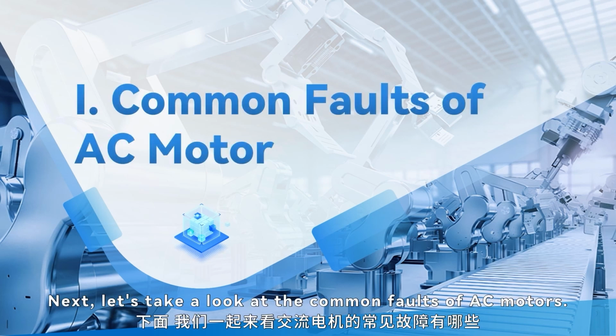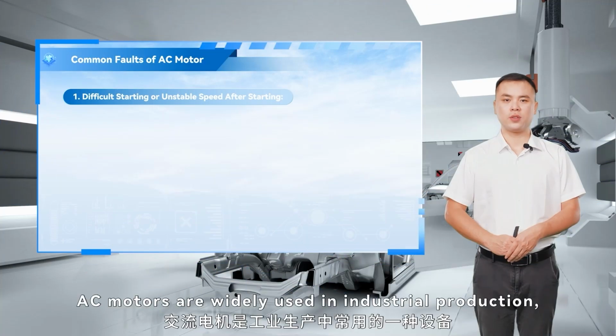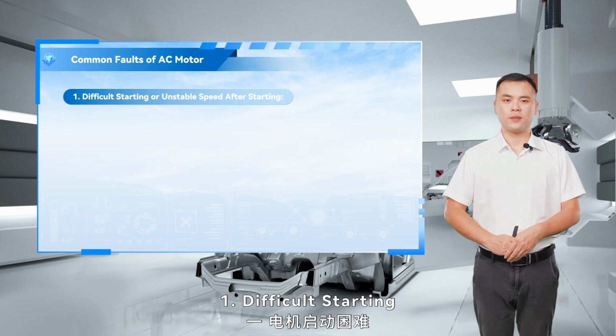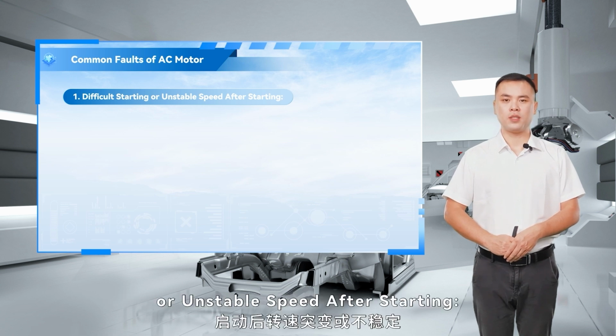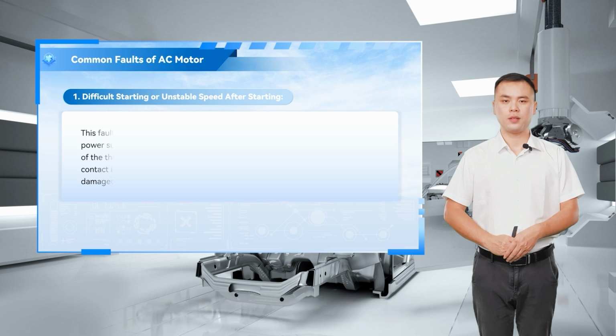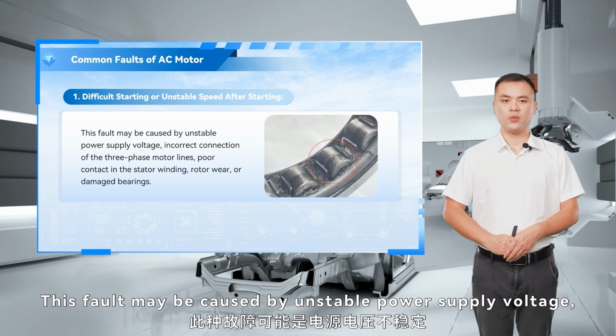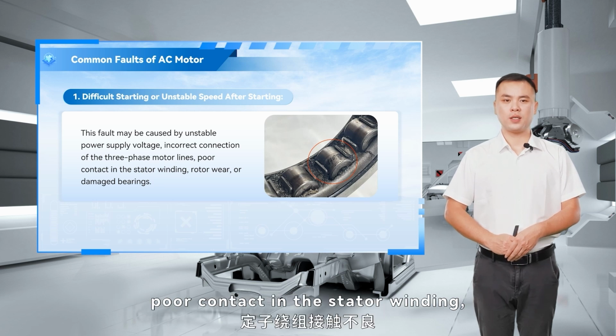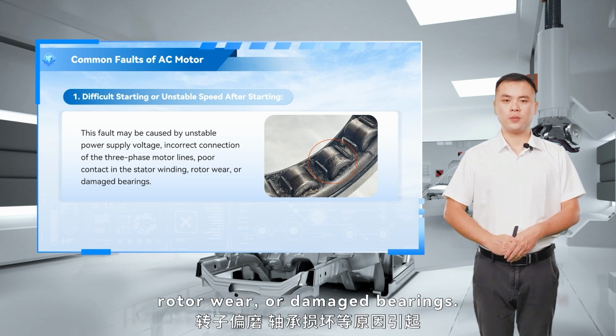Next, let's take a look at the common faults of AC motors. AC motors are widely used in industrial production, and the common faults include the following. 1. Difficult starting or unstable speed after starting. This fault may be caused by unstable power supply voltage, incorrect connection of the 3-phase motor lines, poor contact in the stator winding, rotor wear, or damaged bearings.